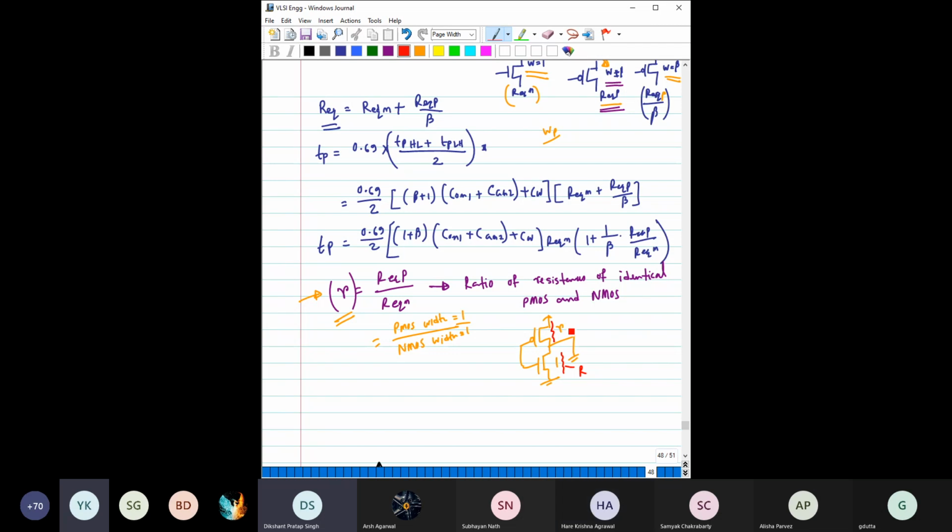Sir, R same. R. Okay. Oh, R. This is R, sorry. I didn't realize you were keeping that part same. Sorry. Then they'll be same. Right. So this is R, this is 1, right? That's what I said, we are making PMOS R times compared to the NMOS, right? So it is R, it is also R. Then that will basically give us the symmetric charging and discharging. TPLH and TPHL should be equal, the same, right? So that is what motivated us earlier, right?